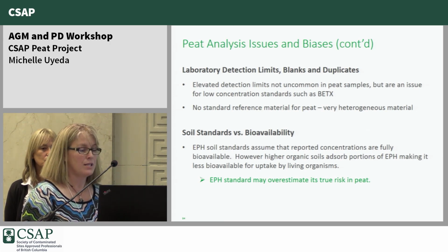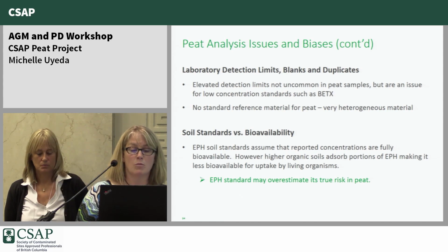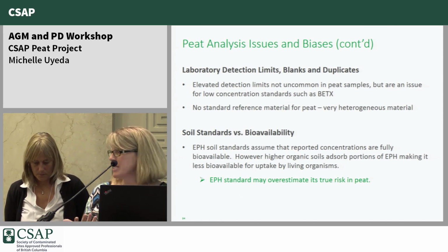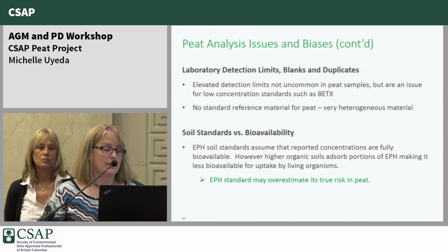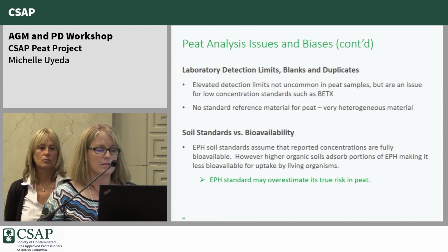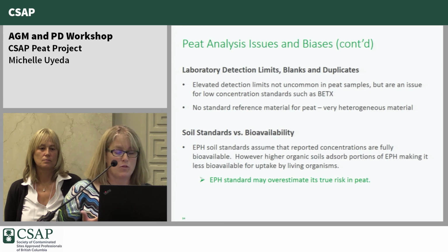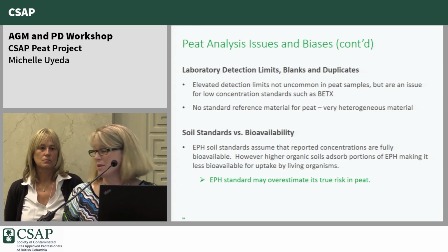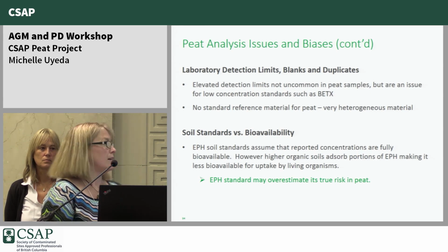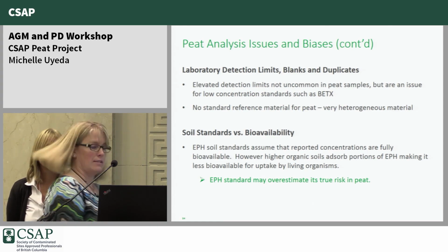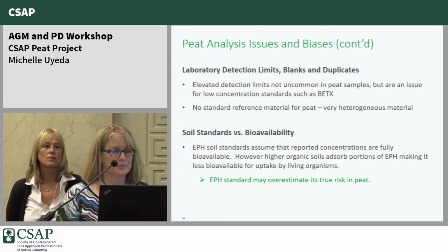So, for example, in EPH, soil standards assume that reported concentrations are fully bioavailable, but in higher organic soils, they absorb portions of the EPH, making it less bioavailable for uptake by living organisms. So, for example, EPH standards may overestimate the true risk in peat. Cindy is going to talk a little bit more about that later on in the presentation.